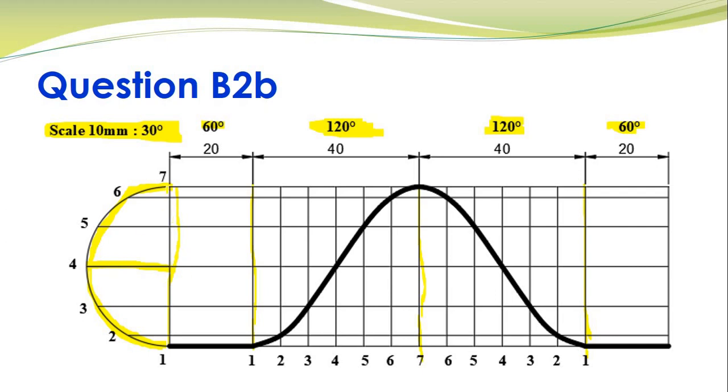So from the center of the stroke, draw a circle. Once you have that, draw this line across, and then keep in your compass the distance equal to the radius. So cut, and then from here you can cut this point, and you can divide this semicircle into 6 equal parts. Then wherever you have made those cuts on this semicircle, you will draw projecting horizontal lines right across as such, and then you will do the labeling.